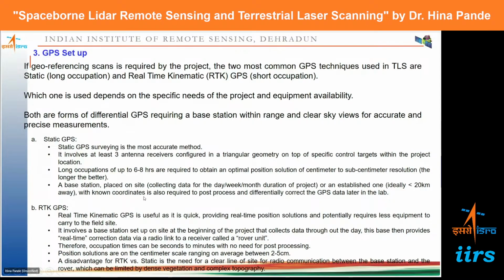The base station, which is placed on site, or we can use an established base station, which is at a distance with known coordinates, is also required to post-process and differentially correct the GPS data. This can be done later on in the lab.